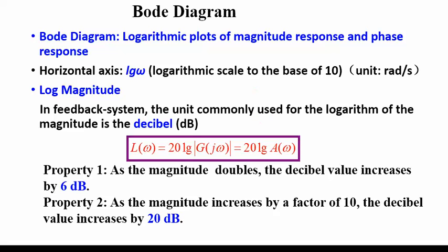What we mean by the frequency response, and just to make sure that we continue from last class, we say that if we have H of s, we transfer it to H of j omega, where we replace s by j omega, and this has the magnitude of H of j omega times the phase angle of j omega.